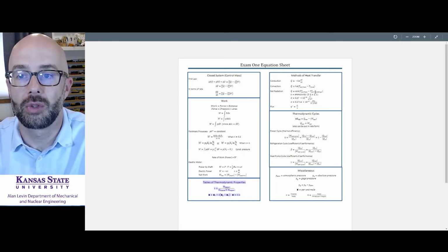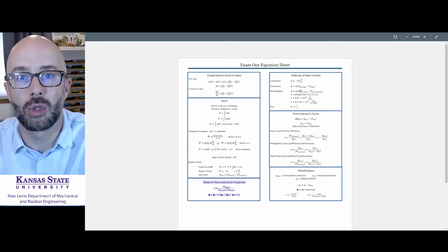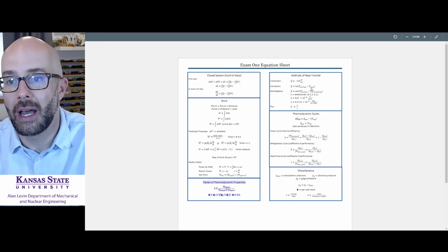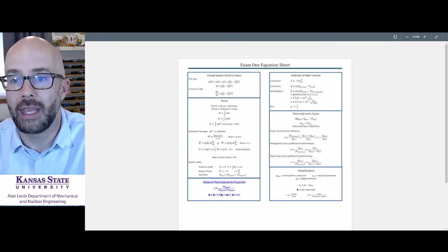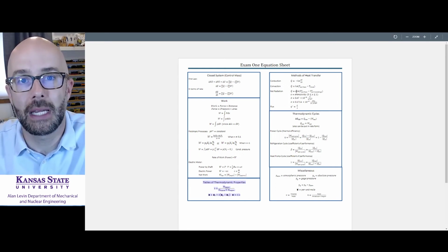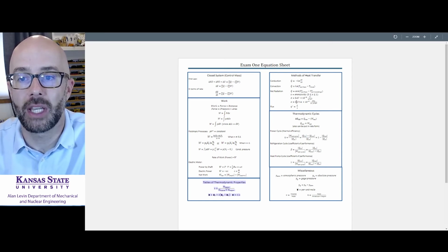And you know this is the only one that you have to have absolute temperatures in. The other two, you can have relative temperatures as well. I gave you the emissivity. I'm going to have to give you the emissivity in the problem. It's going to be between 0 and 1. And I've given you what sigma is for both unit systems, for SI and for English systems.